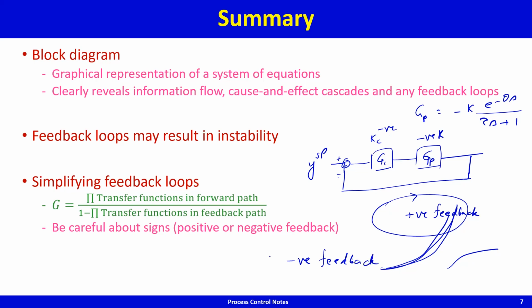And when you're doing control, so for example servo response, this is when you can expect this kind of a servo response. And of course, even in negative feedback, you could have that Kc is too large. If the feedback is too large, you do get oscillations, but then the oscillations tend to blow up.